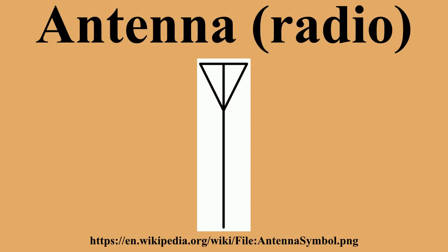Therefore, in discussions of antenna properties, no distinction is usually made between receiving and transmitting terminology, and the antenna can be viewed as either transmitting or receiving, whichever is more convenient. A necessary condition for the aforementioned reciprocity property is that the materials in the antenna and transmission medium are linear and reciprocal. Reciprocal means that the material has the same response to an electric current or magnetic field in one direction as it has to the field or current in the opposite direction.